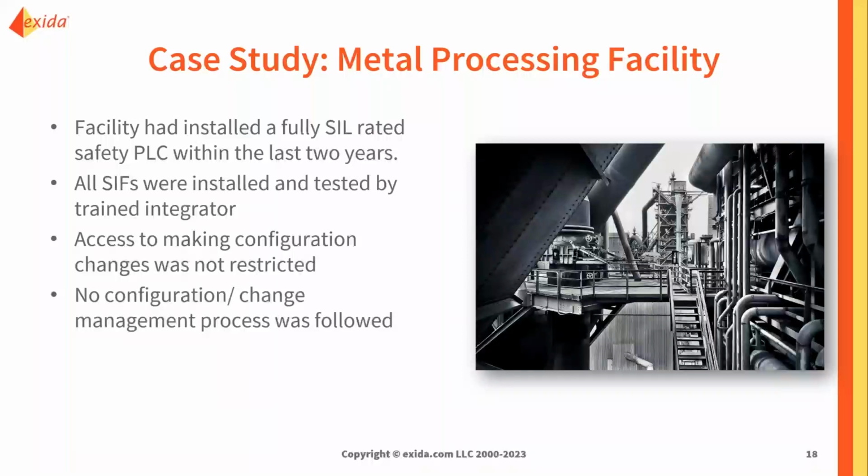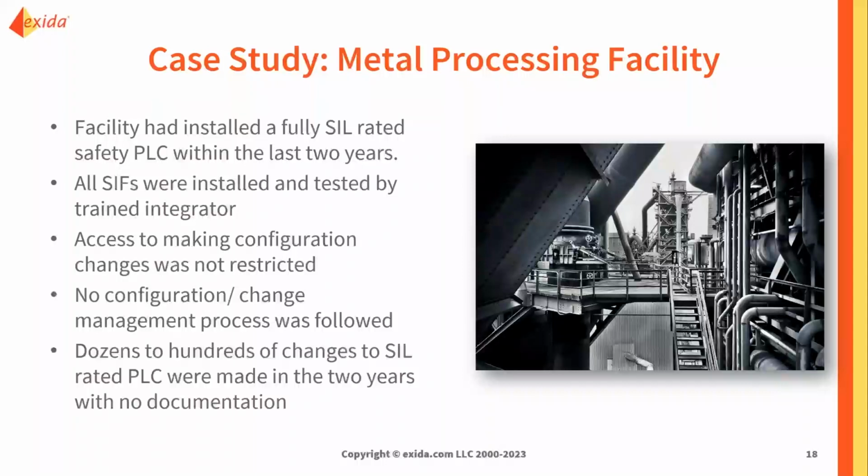So we really weren't restricting or controlling those changes. We found out a little bit more, there also wasn't any configuration or change management process that had been followed. So there was no formal place to document changes. There was no formal process for understanding whether or not a change could have a safety impact. And finally, by the last day, we realized that dozens to hundreds of different changes had been made to that safety rated PLC in the last 2 years. No documentation, no information about what types of changes have been made, who made them, any of that.